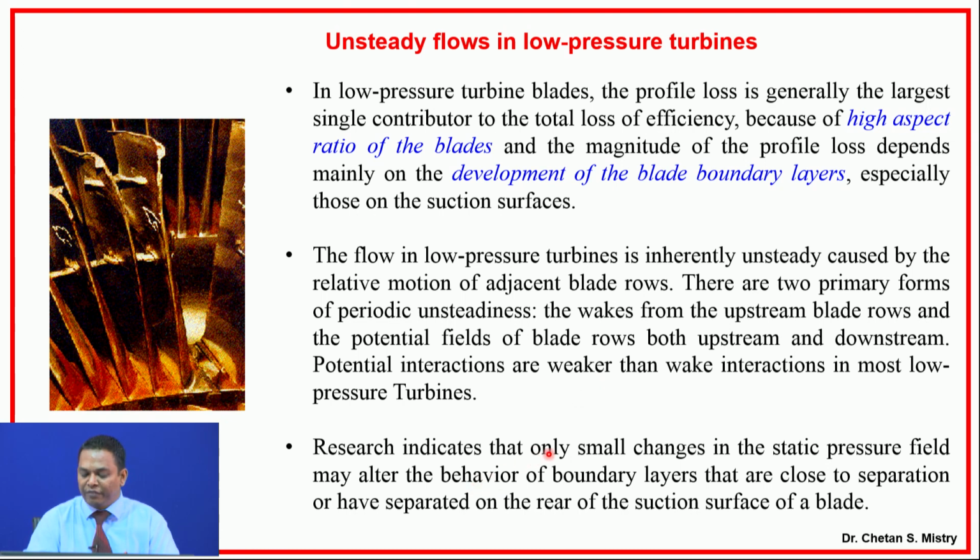Research indicates that a very small change in the static pressure flow field may subject the boundary layer to separation, giving separated flow on the rear side of my suction surface. That is what we have observed.